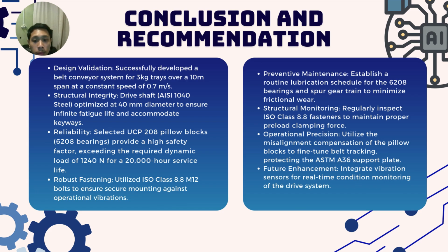From a safety perspective, by using AISI 1040 steel for the drive shaft and ISO class 8.8 bolts, we have ensured the system is resistant to fatigue and vibration. Furthermore, the selection of UCP 208 pillow blocks guarantees a reliable service life of 20,000 hours, making this a robust solution for industrial transport.